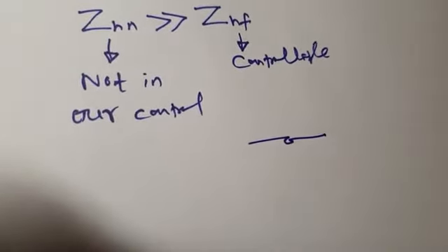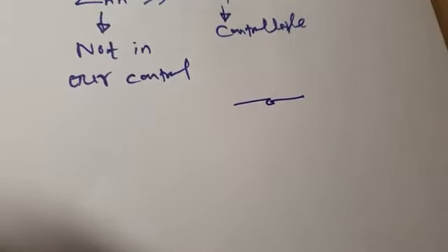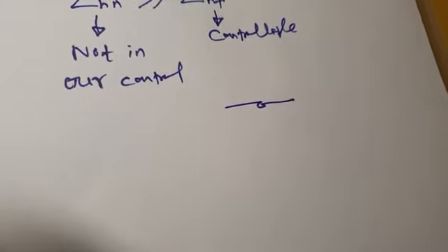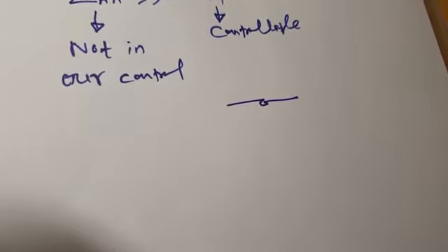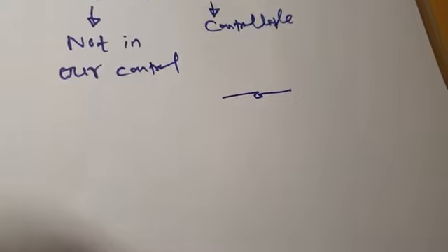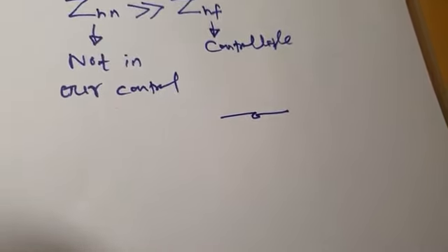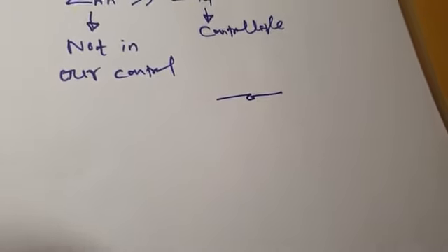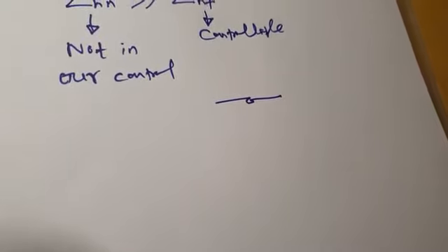With this I will complete my today's lecture. In today's lecture, we discussed the design aspects of a single tune filter, the conditions for designing a single tune filter and then a double tune filter, and how much reactive power is compensated or generated by a single tune or double tune filter. We have the mathematical expression for that, and we have seen that reactive power is always generated by the harmonic filter. It's not absorbed. It always generates reactive power.